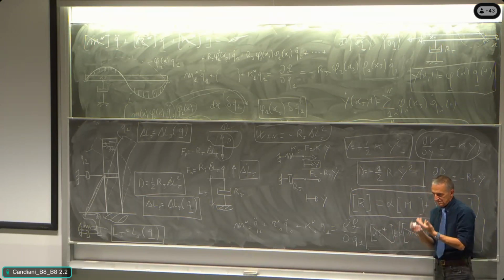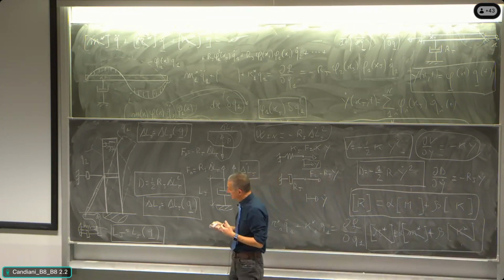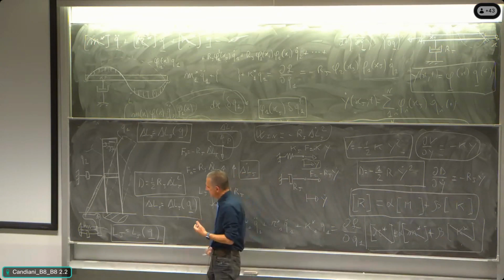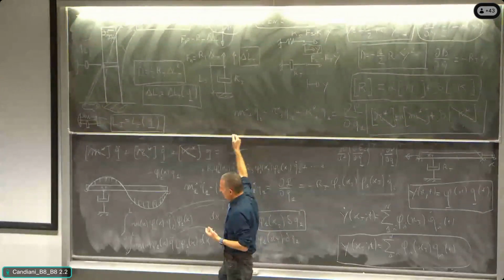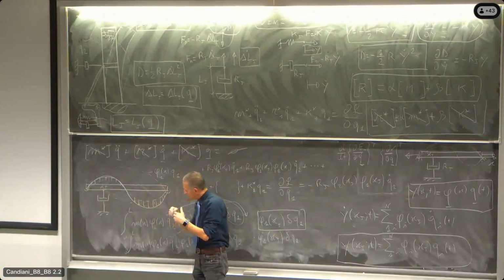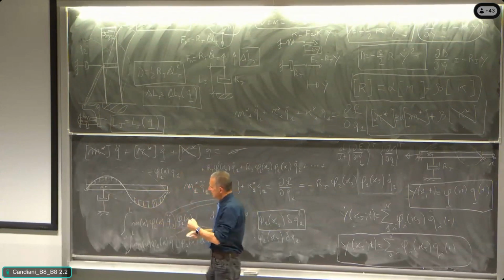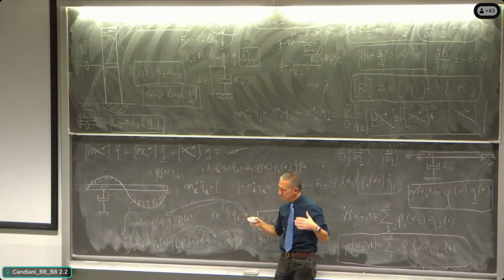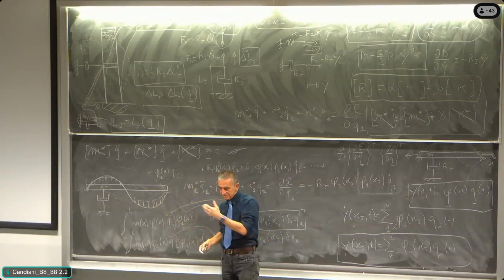But the idea is that with this modeling, you keep the property of the damping matrix being diagonal, because you are not associating the work of a virtual displacement in one mode to the distribution of the damping effects on another mode.